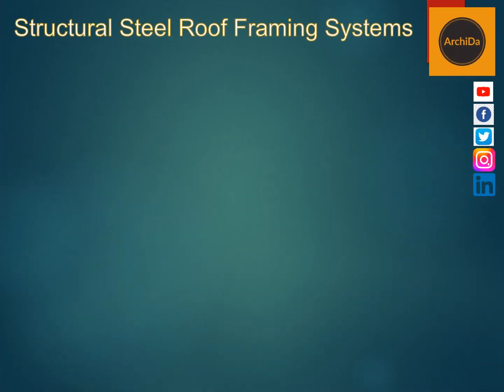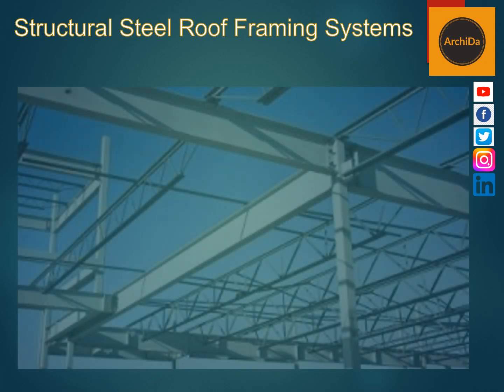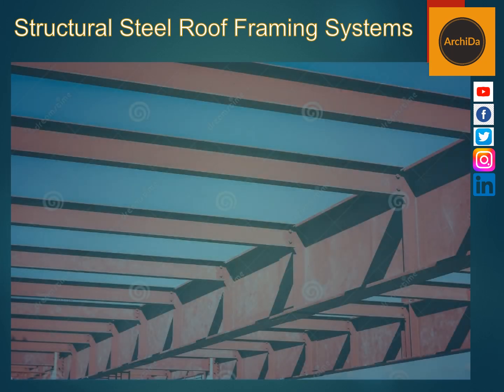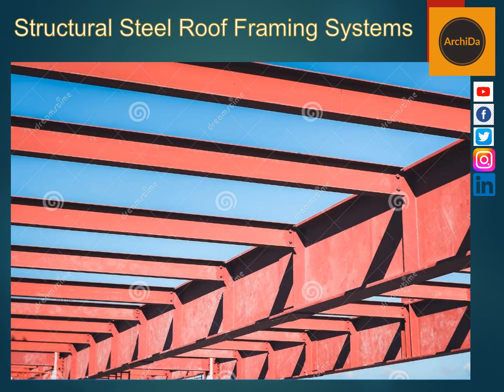Long span steel framing. Long span steel framing is considered when large clearances are required and such long spans cannot be realized using steel beams and columns. Long span steel framing options can be categorized into different types, for instance, girders, trusses, rigid frames, arches, and cantilever suspension spans.